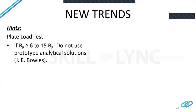Another aspect is the plate load test. Usually, plate load tests are used to verify the bearing capacity or the modulus of subgrade reaction of the foundations using the analytical solutions, for example, in Joseph Bowles. This test is very useful for us if properly used, but in a lot of cases, it has unfortunately been misused.